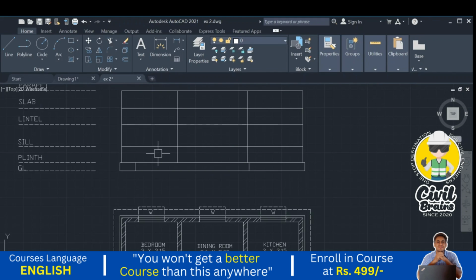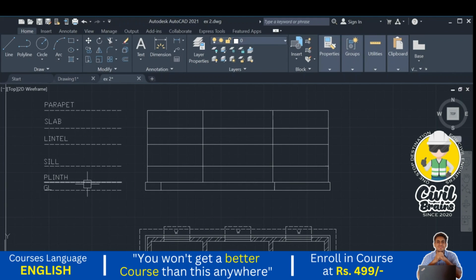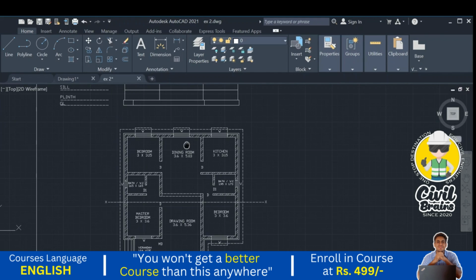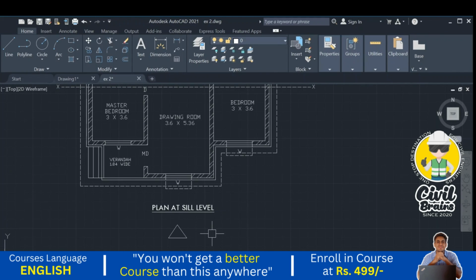Okay, this is our front elevation. So we mark the plinth level, we mark the sill level, we mark the lintel bottom level, we mark the slab bottom level, we mark the parapet level. Okay, so next, now you just stand in front here and see what is visible from this corner. You just start. What is visible? Steps, then veranda, then this wall, then window, then veranda. Okay, we'll start from here.